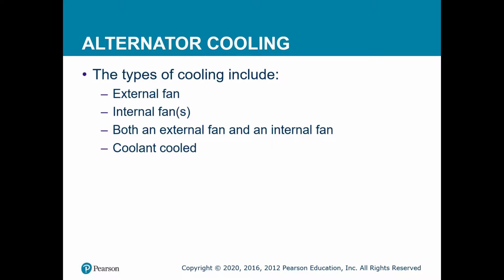So obviously heat is a major concern with a charging system. So cooling that charging system is very, very important. Now, up here I've got a few examples. We have an external fan, which I believe was in that breakdown or mock-up of the alternator, but they also have internal fans. So you'll have a fan inside the case to pull heat out, and the external fan to help pull cool air in and also assist in pulling heat out.